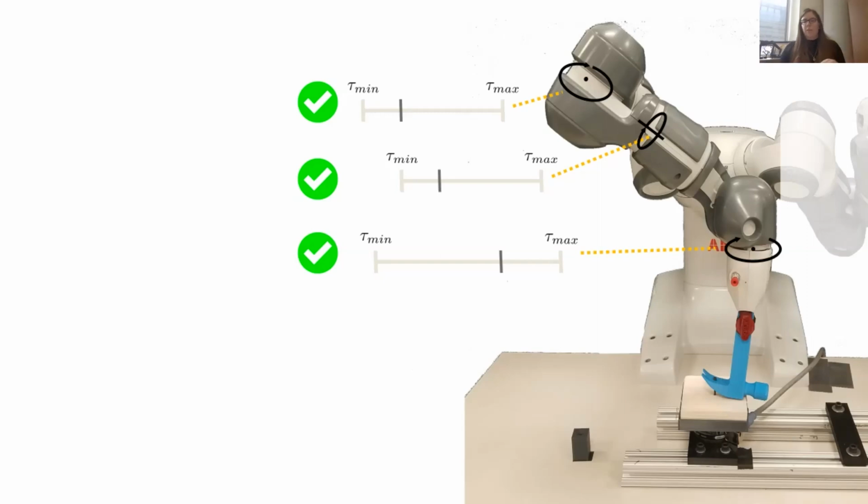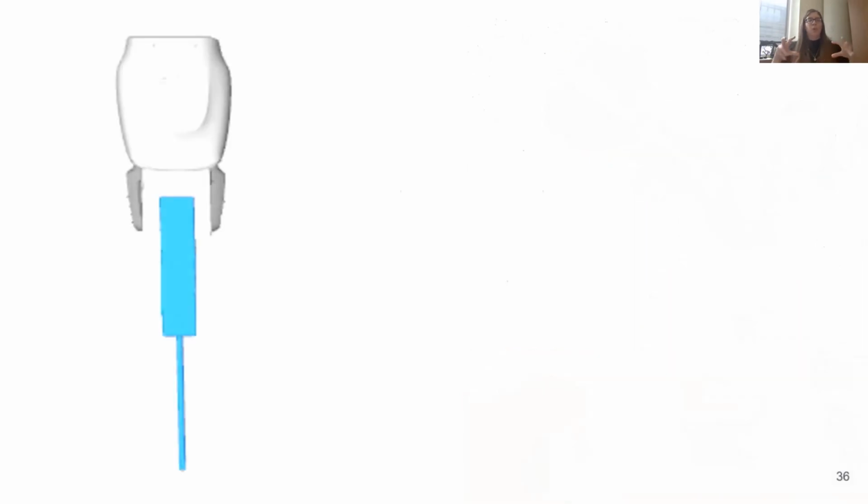The other kind of joint that we mentioned is the frictional joints. And these are specifically, in this case, formed by the grasp of our robot on our tool. So how do we quantify how strong this joint is? What is the set of wrenches that this joint can resist? To answer this, we're going to zoom in on what type of contact we're making.